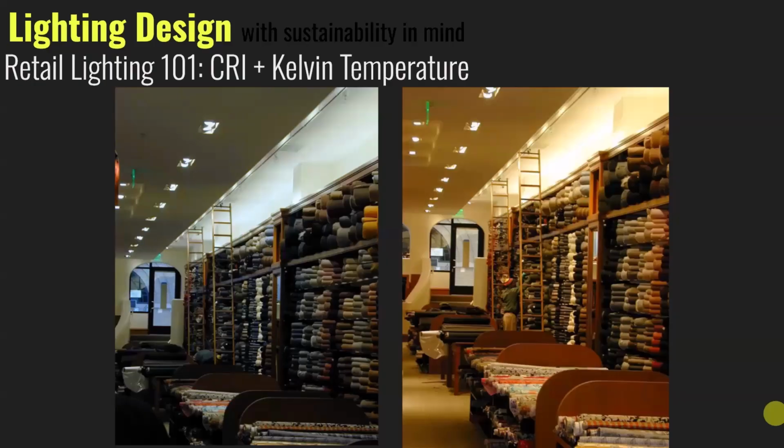Okay, I would say something more like a 3000 Kelvin versus that really warm 2700 would make a big difference still. But again, different shops have different ideas, different branding, and I think it does create a homier, more comfortable atmosphere. And the atmosphere, along with color rendering for product, is an important balance. Yeah, this is 2700 now. I would argue that 3000 Kelvin would be as warm as I would go for something where color is so important. Because 2700 Kelvin, even in LEDs, is not going to give you the same color rendering.